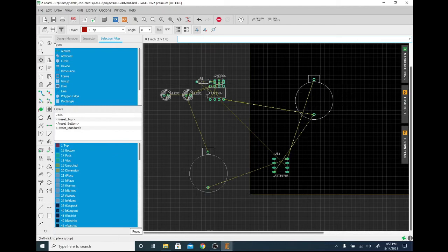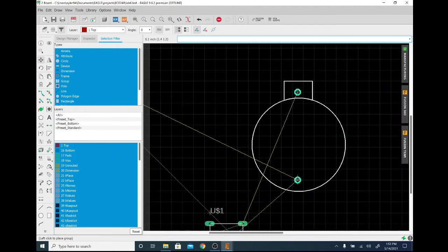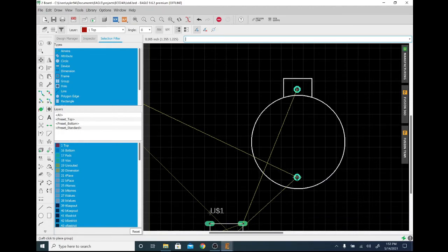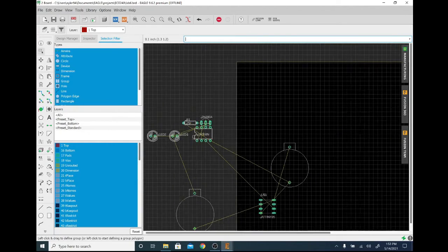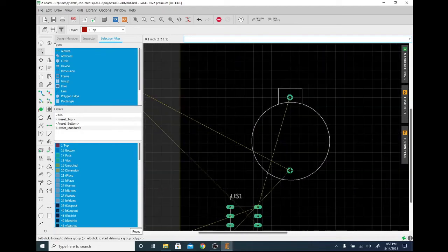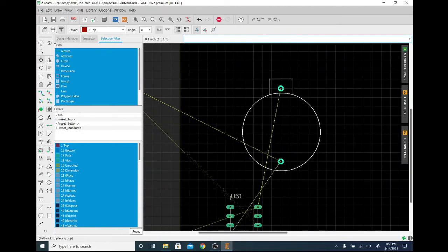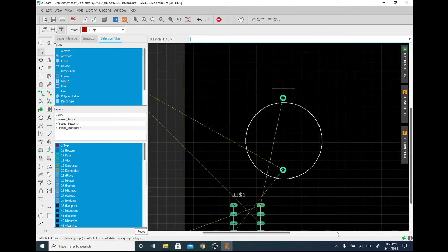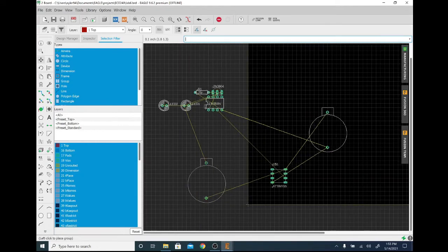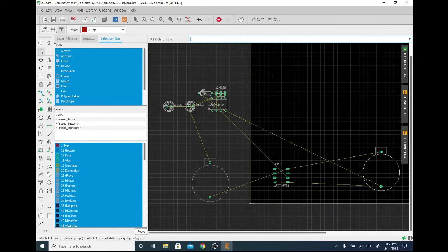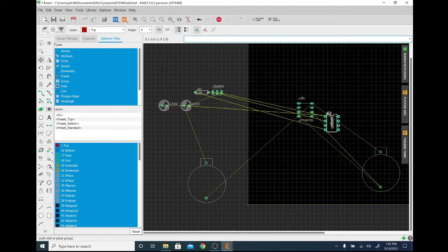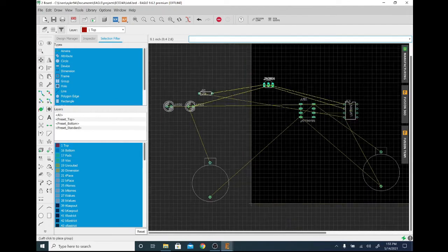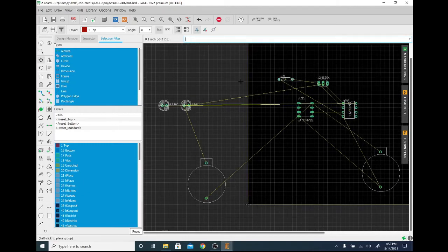I mean, that could be really, really annoying, especially if you need to do finer motion. So what I'm going to do is I'm going to hold that Alt key, and now it goes to my alternate grid. And so then I can place it exactly on those crosshairs, and I'm not worried about trying to fuss with that. But now if I'm not holding the Alt key, it'll let me go back to my gross movement. All right, so now that I've explained the alternate grid, let's go ahead and lay out a kind of a gross, meaning large, not gross isn't disgusting, a large layout for where our parts are going to go. And you can see these yellow wires represent the connections that need to be made, and they're kind of going everywhere. It's really ugly. It's not very clean.